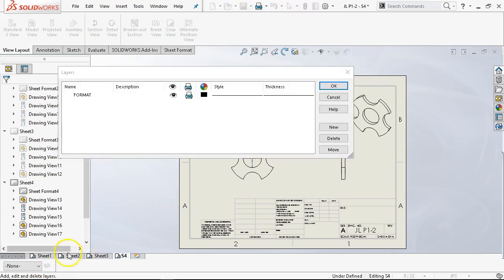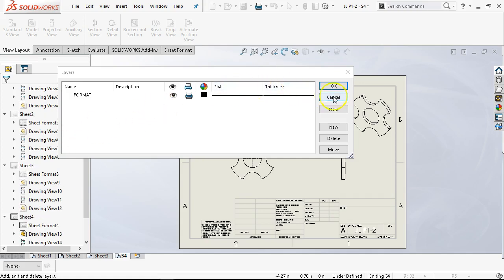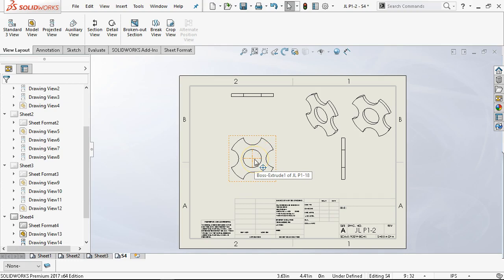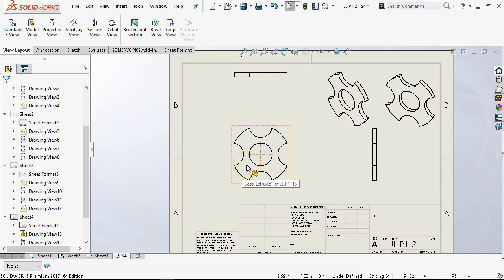So this is very similar to what you would see in the Autodesk products: setting up a layer, line color, line types. We would go through and set a dimensions layer and save it to the template. Set our construction lines. Probably the main difference is that in AutoCAD I would use maybe 20, 30 layers. If I get to 3 layers in SolidWorks, I'm doing good. I can't hardly justify getting more than about 3 layers.